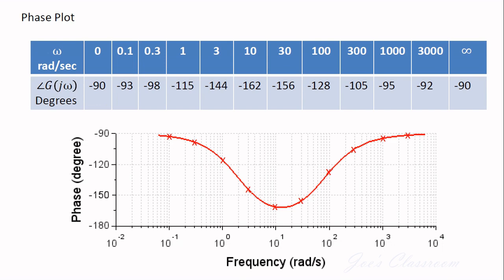That is one point. And the other point is that the main application of this Bode plot is system identification, in which we will have the Bode plot and we may have to get the transfer function back. We have already seen in the previous lectures that to generate the transfer function from the Bode plot, only the magnitude plot is sufficient, not the phase plot.